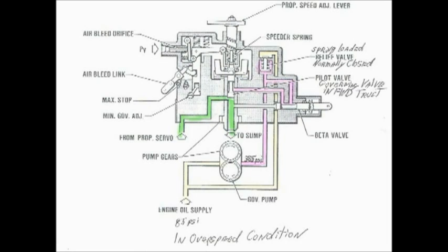So right now this is a picture of it being above the prescribed speed. In the feathering position, the governor pilot valve, that's this one right here, is raised mechanically to decrease the oil pressure in the propeller. So when this valve is raised, it will decrease oil pressure that goes to the propeller. In the beta range, oil pressure to and from the propeller is metered by the beta control valve through the mechanical lever and the feedback ring.